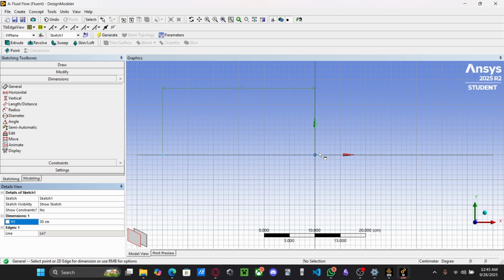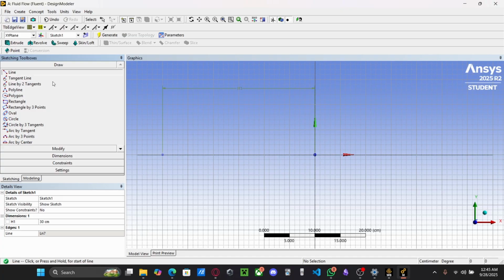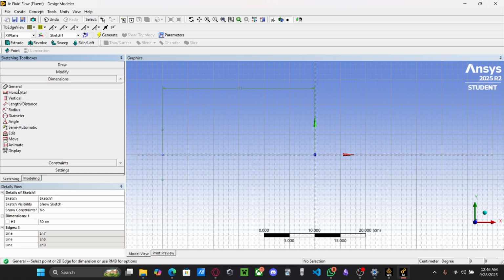Now you notice that the diameter for this side here should be 7. So what we can do is 3.5 above and 3.5 below, right? Let me draw this line again. From this point, let's just extend it, and from here, let's just extend it. Now same thing again, we take the length, and you can see this is 5. We want 3.5, so 3.5, press enter, and the same thing here, 3.5 and enter.